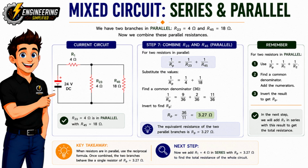One branch has an equivalent resistance of 4 ohms, and the other has an equivalent resistance of 18 ohms. Since these two resistors are connected across the same 2 points, they are in parallel. So once again, we'll use the parallel resistance formula. 1 over R sub P equals 1 over R23 plus 1 over R45. Now substitute the values. 1 over R sub P equals 1 over 4 plus 1 over 18.